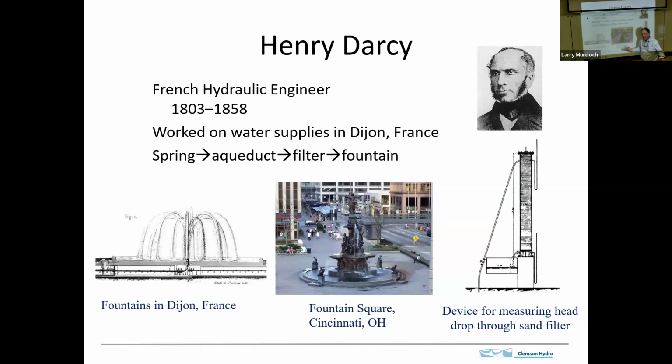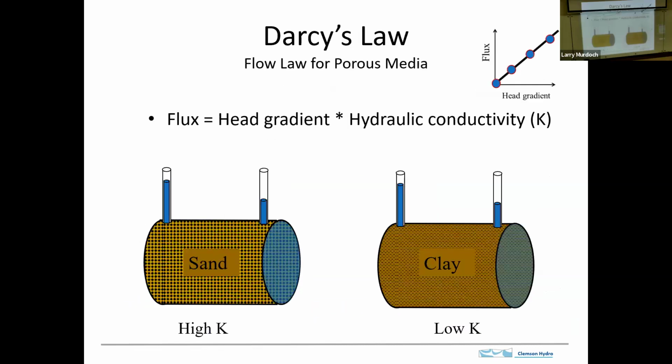Okay, so he figured out this relationship between the flow and the hydraulic head, and it turns out he just did it experimentally. He just did a bunch of flows and measured a bunch of head gradients and found they were linearly related. It turns out it worked well, and it was really key to doing the calculations for flow through porous media.